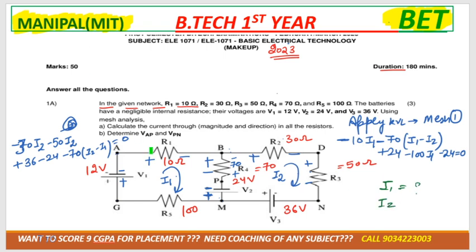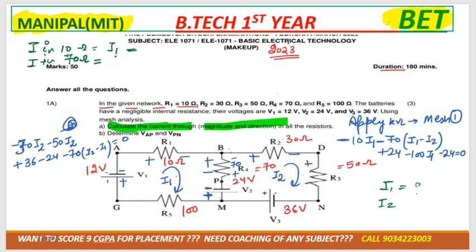But see, read the question, what they said. They said calculate the current, magnitude and direction, in all the resistors. So basically you need to attempt it like this: current in 10 ohm is how much? Suppose I1. Write down the value for I1. Next, current in 70 ohm. Okay, 70 ohm would be how much? I1 minus I2. So write down the value.